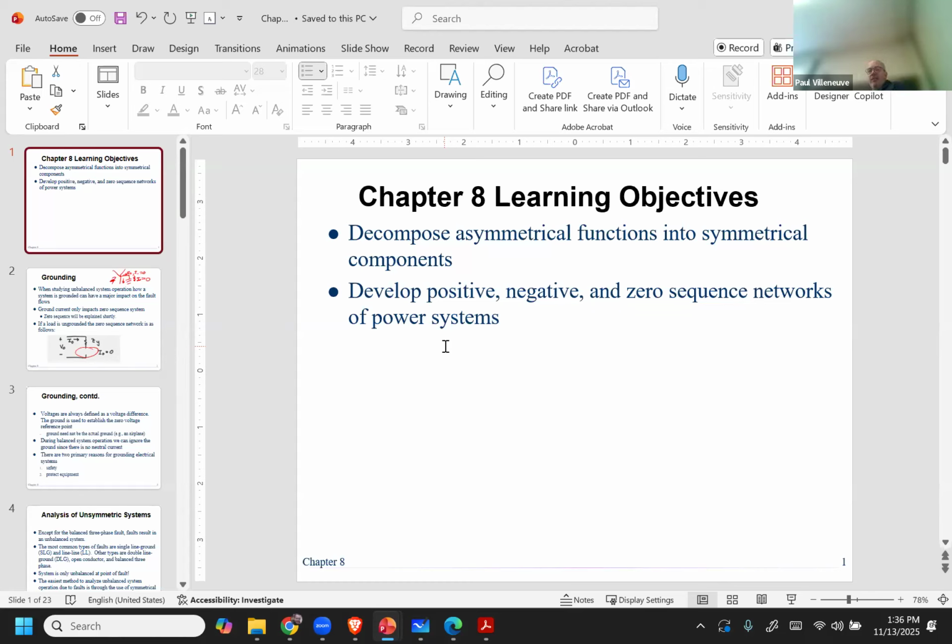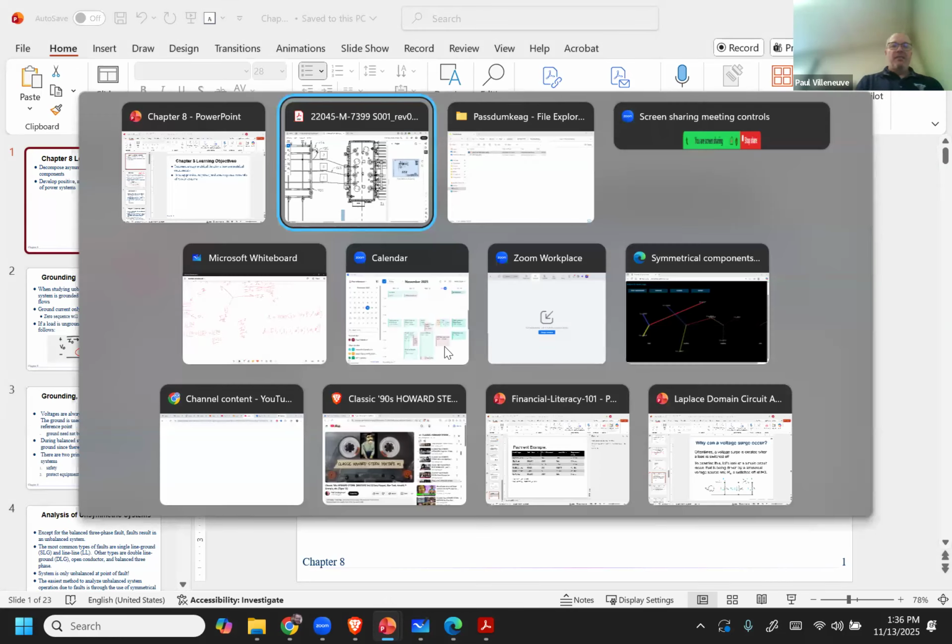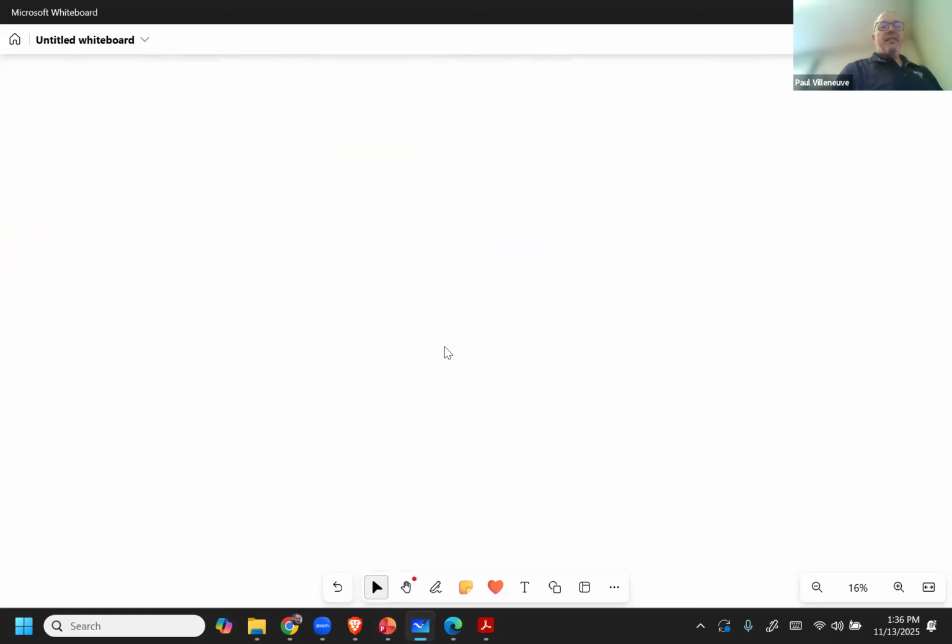And again, the reason why we talked about a distribution circuit. So a distribution circuit might have a Y ground, if it's like for a Walmart, essentially. So a Walmart usually has a Y grounded like that. So this is 480 volts, 5 MVA, decent sized transformer. The reason why they do that is because with 5 MVA, what are you talking about for a current? Not very much. So if they have a ground, they'll just rely on the phase elements to trip it. So if you have a fuse, the fuse will trip it off.